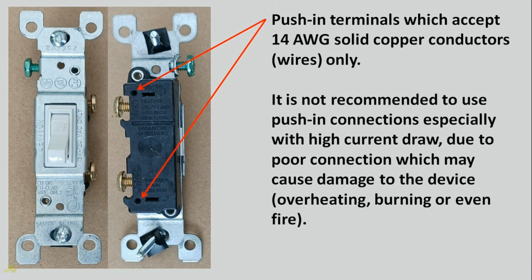Push-in terminals accept 14-gauge solid copper conductors, wires, only. It is not recommended to use push-in connections, especially with high current draw, due to poor connection which may cause damage to the device, overheating, burning or even fire.